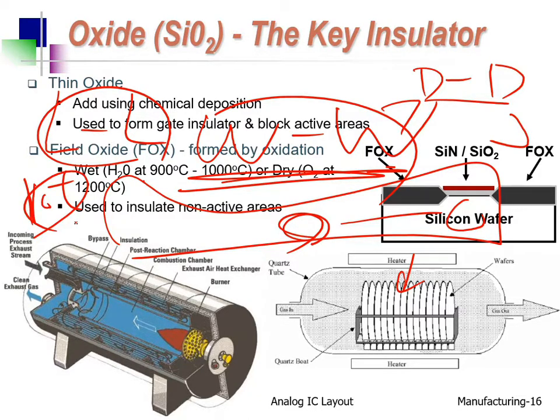Okay, so with this very good example, I not only show you why we have systematic mismatch, but also I tell you why the lot to lot mismatch will be larger than wafer to wafer, then die to die, then on die mismatch. But why lot to lot?